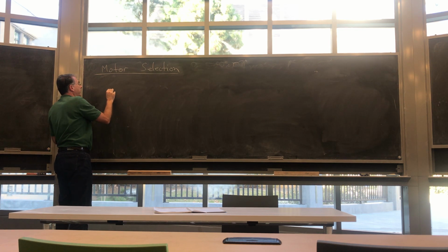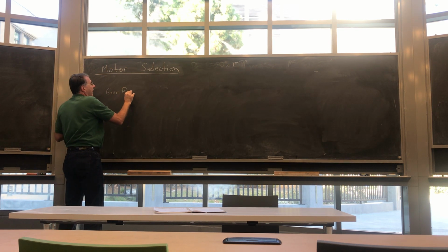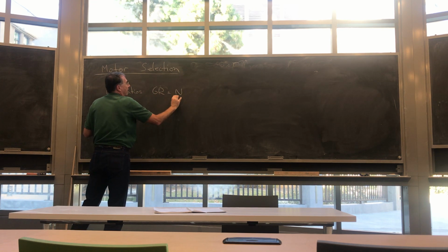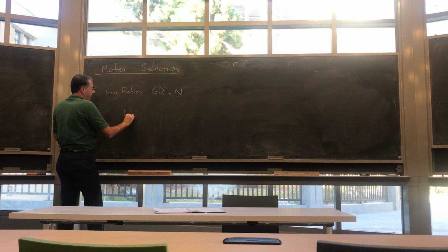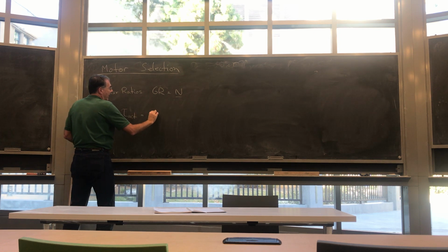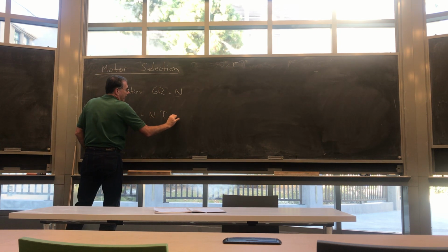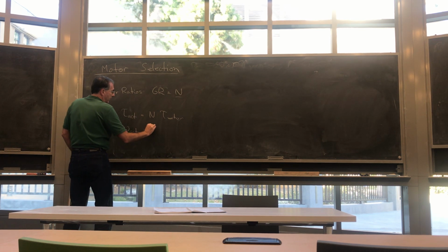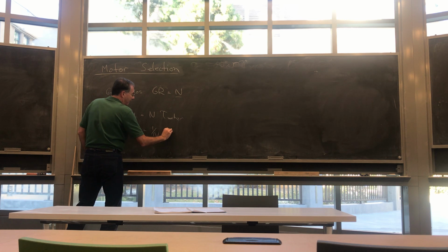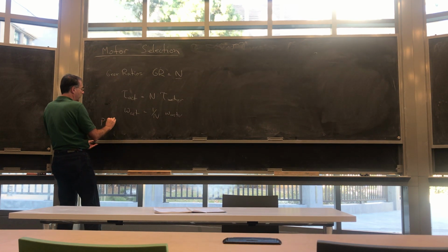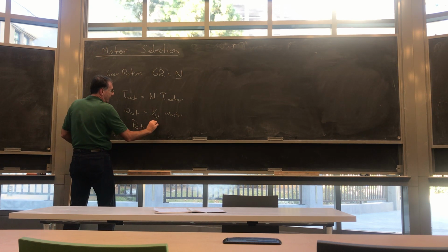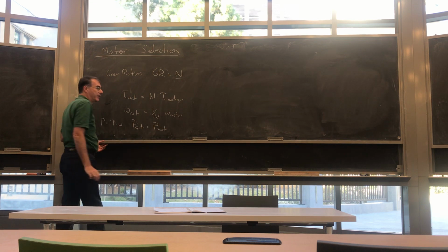But do you guys remember we talked initially about gear ratios on motors, which is usually a capital N, meaning the tau of the actuator is N times the tau of the motor, because you could put it through gearing. But as a result, the speed is 1/N of the motor, which also means if you look at the power, which is the product, right? The power of the actuator is the same as the power of the motor. A gear is just a gear, it doesn't add any power.